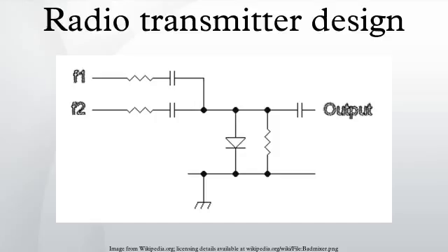FM modes. Angle modulation is the proper term for modulation by changing the instantaneous frequency or phase of the carrier signal. True FM and phase modulation are the most commonly employed forms of analog angle modulation. Direct FM is where the frequency of an oscillator is altered to impose the modulation upon the carrier wave. This can be done by using a voltage-controlled capacitor in a crystal-controlled oscillator or frequency synthesizer.